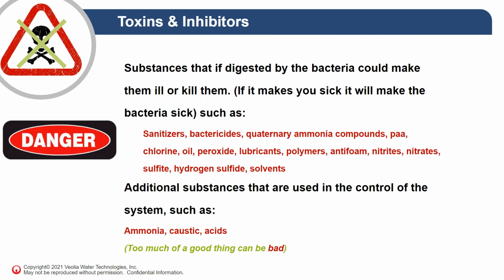are in the wastewater. And there are companies out there now that say that they have chemical compounds that will neutralize quaternary ammonia compounds and PAA. Some of them I've heard work quite well. The issue with me in using these is that it's hard to tell how much of them to use. Unless you run it off the ORP measurement and adjust the concentration that way, it's awfully hard to tell how much you need to do that neutralization and kill the toxicity, if you will.